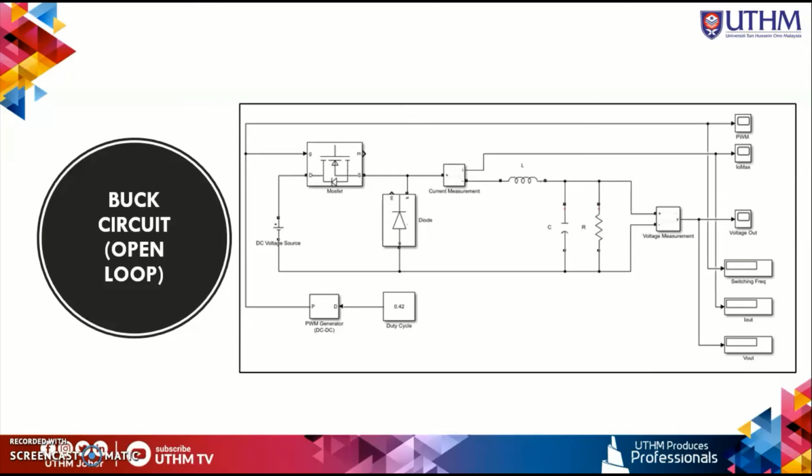Okay, this is the circuit that we construct that uses the open loop. This is the construct of the buck circuit without the PID. So we can see that this circuit is open loop because there is no reference output from the output voltage coming back to the MOSFET.